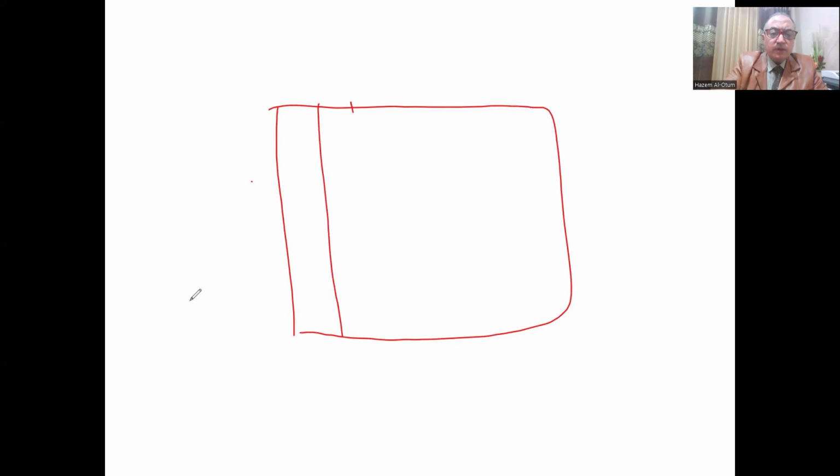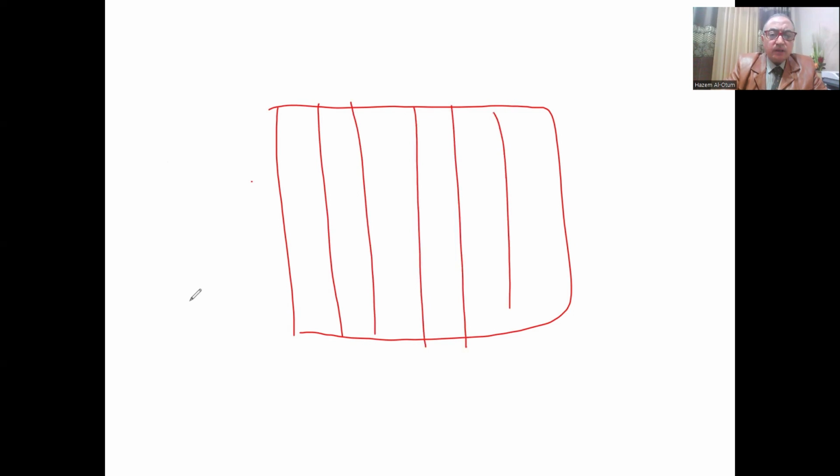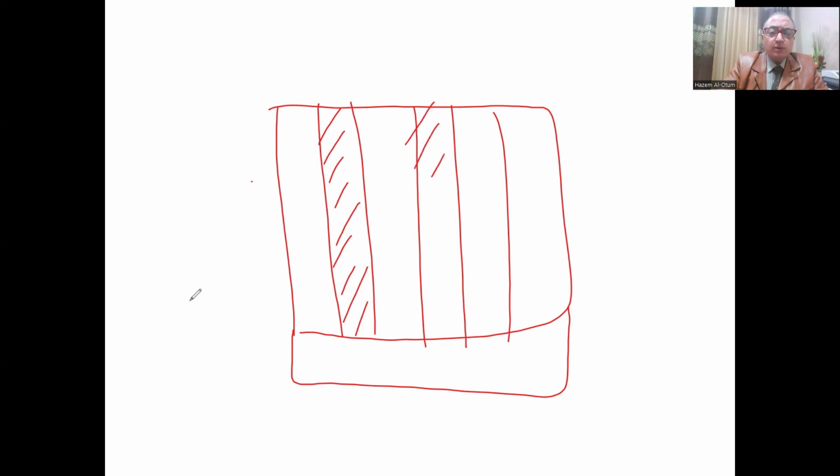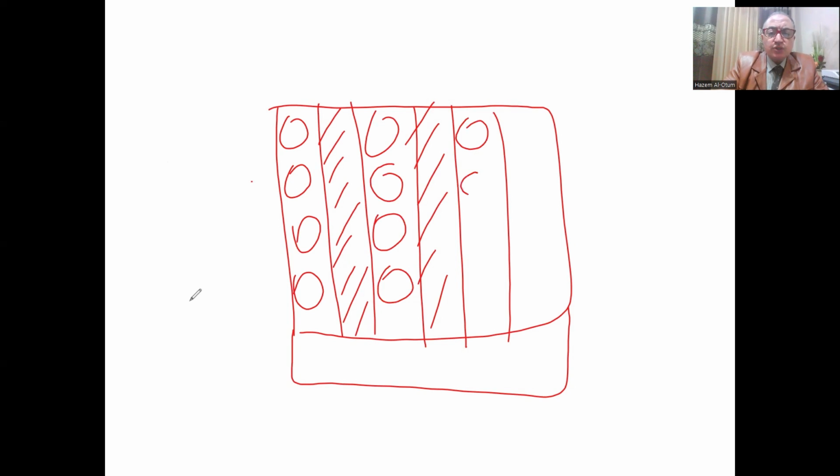Okay. Here, suppose that this is the image CCD camera. This part, let's see this one. Now, this row and column will be masked. This one is also. Now, suppose that we have light here. The charges are concentrated by the light incident to this chip. Okay. Next, after shuttering, these pixels will be shifted to the masked area.